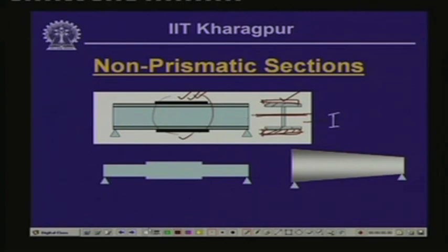As you have seen, the bending stress sigma is equal to M y by I. If we increase the value of I, then the value of sigma comes down, and thereby this will be more effective in carrying the stress if we can increase the moment of inertia in the central region. If we do that, then this particular beam becomes a different section, a variable cross sectional area.